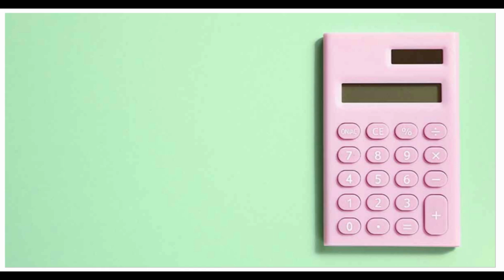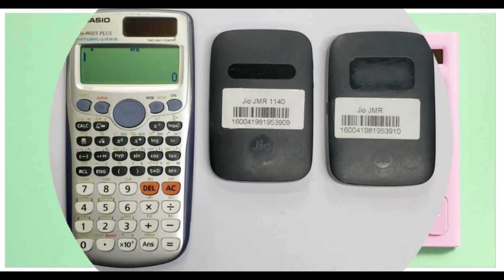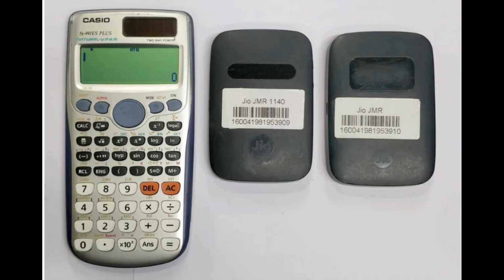A designer might choose to use a series of separate identical 7-segment displays to build a metering circuit, for example. If the numeric quantity were stored and manipulated as pure binary, interfacing to such a display would require complex circuitry. Therefore, in cases where the calculations are relatively simple, working throughout with BCD can lead to a simpler overall system than converting to and from binary. For example, CDs keep the track number in BCD, limiting them to 99 tracks.